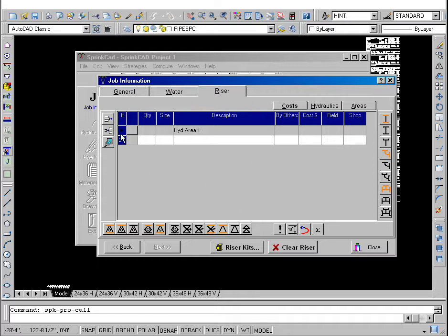Pick and highlight the row below row 1 and press the down arrow key on the keyboard. This will move the black arrow to the second row. Items are always inserted in the row above the position of the black arrow. Select the Insert Row button.